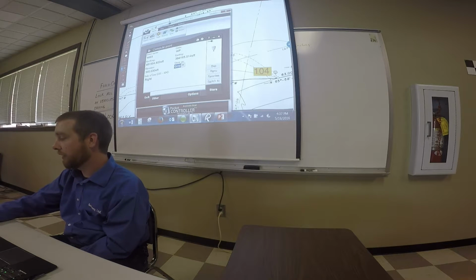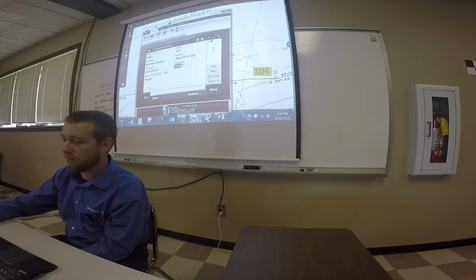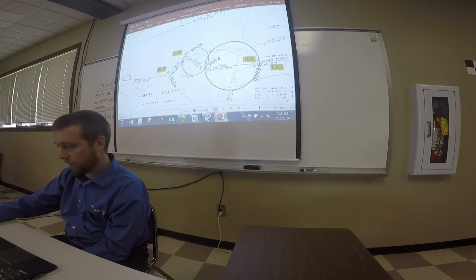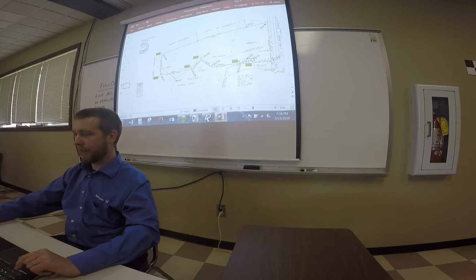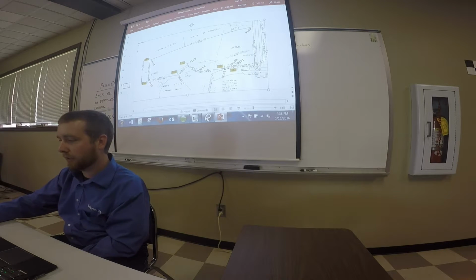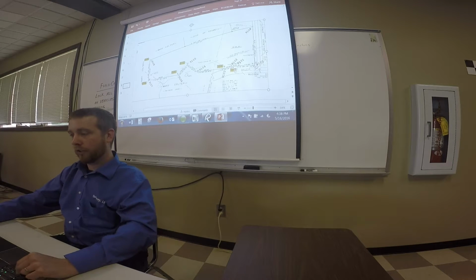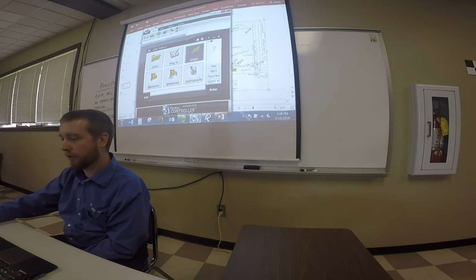Now we're going to run through translate and rotate. We've got a printout already, with all these 9,000 numbers given to us. So let's just pick two points. We're going to go with 103 and 845, and we'll inverse those two and see how they check.